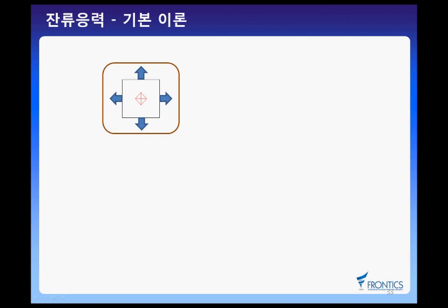For example, as shown in this figure, a stress field is induced by indentation. This hydrostatic stress influences elastic volume deformation in the core during indentation, whereas deviatoric stress influences plastic deformation. In particular, z-directional deviatoric stress is believed to affect the shift of the indentation load depth curve.